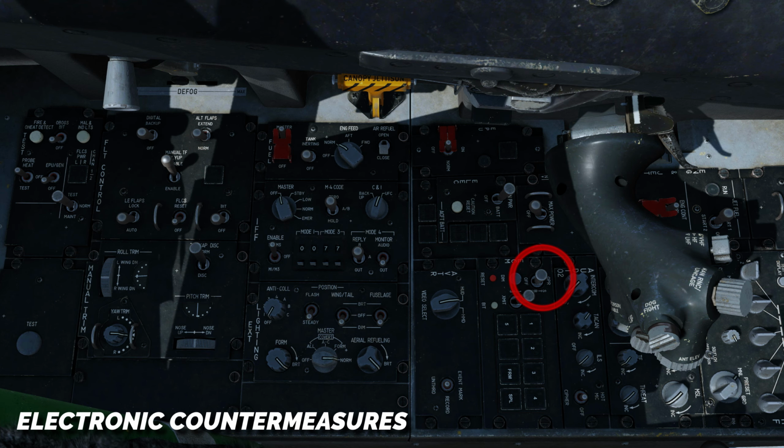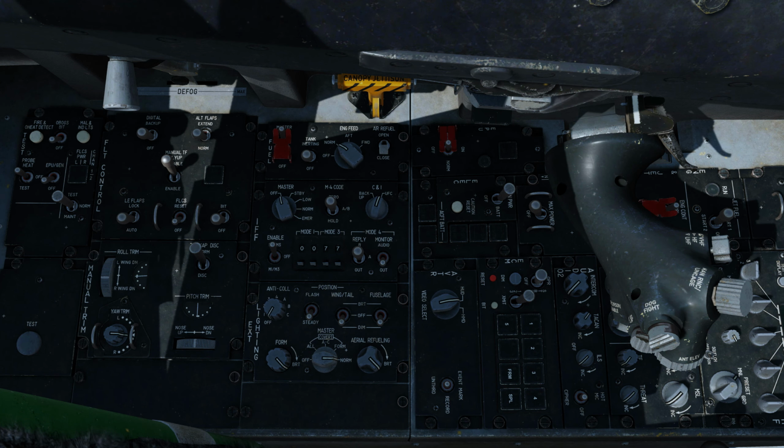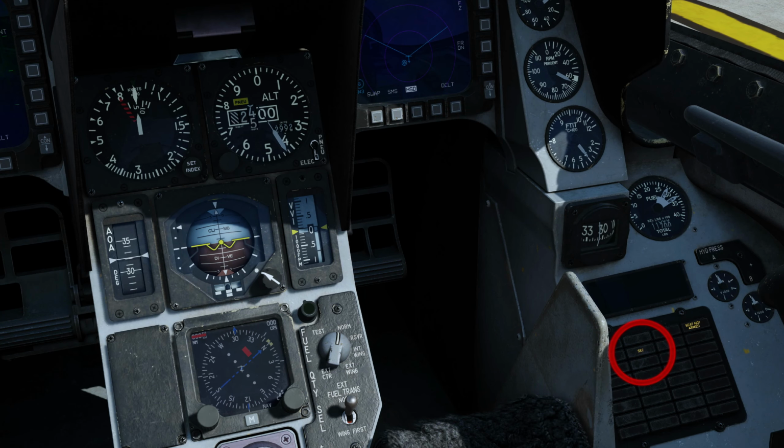ECM is in the standby position. We will now test secondary control mode. Apply toe brakes. To select secondary control mode, place engine control in the secondary position. Master caution and the secondary caution light illuminate. The engine nozzle closes and the nozzle position indicator should report less than 5%, with 0% being completely closed.